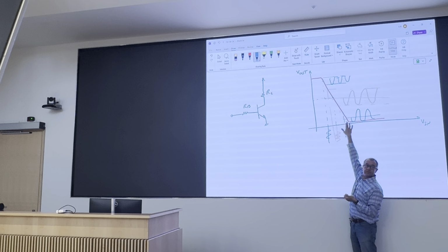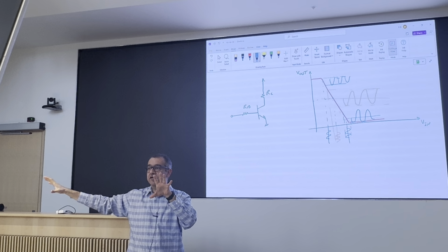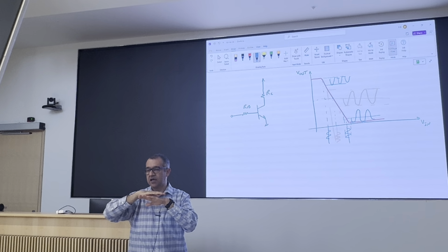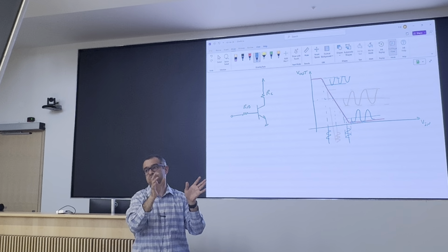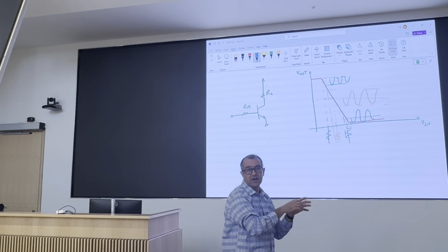Is this why microphones can peak? Like, if it's too loud, the microphone kind of just peaks. Which one do you mean? The high frequency pitch? Oh no, just like feedback. Yeah, that's clipping. It's one amplifier in the chain of amplifiers that is hitting the top rail. It could be the very first one, which means you clipped right at the microphone, or it could be somewhere else in your audio system. Okay, got it. It's one amplifier in that chain that is doing its job.